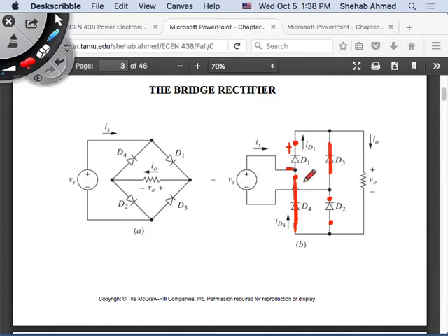It sees what? So this is this diode voltage. And if I go around, let's say I go around the loop here, I see this diode voltage, and I see 0. Let's go around this loop. This is a closed loop, an easy closed loop to go around, right? Current is coming out of here, going through D3, going back to the output and coming back through D4. This is my closed loop here, right?